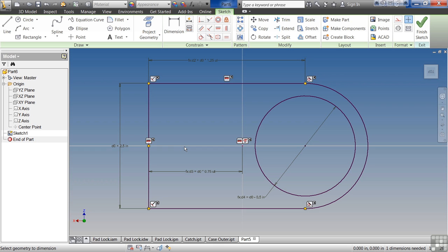When you're capturing design intent, it's always good to identify the geometric relationships first. For example, this being perpendicular from one line to the next. This line being tangent to the circle, whereas this line is tangent to this half of the circle. Then identify areas that are prone to change as a result of design problems. I know that this width is going to change, but this is always going to be 1.25 times. So I set up the dimension to be this is the driving force, this is the flexible force that's based on this dimension. Identify areas of symmetry.